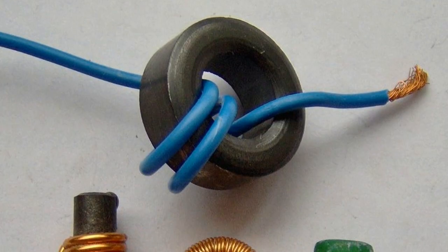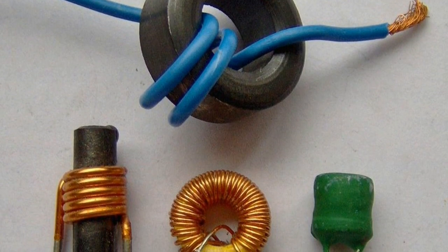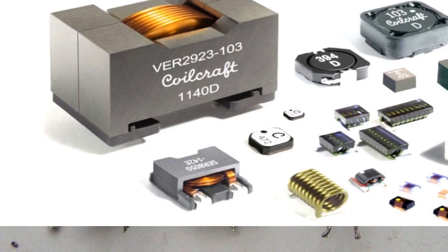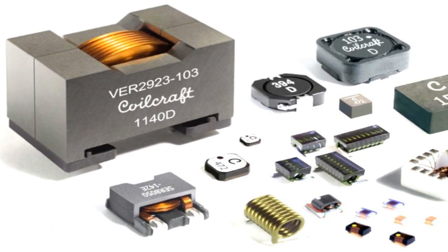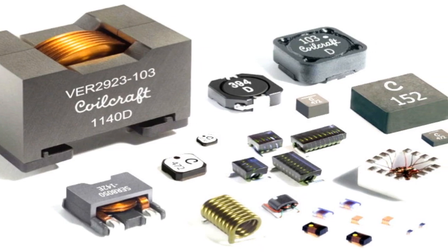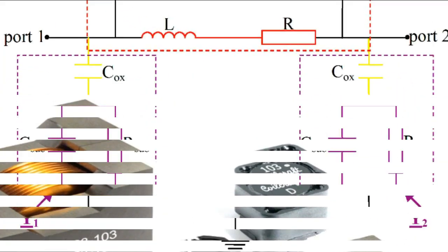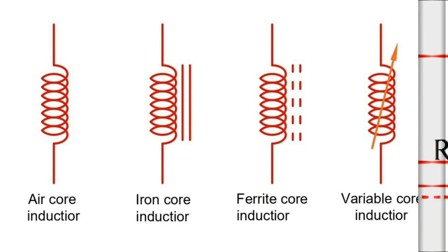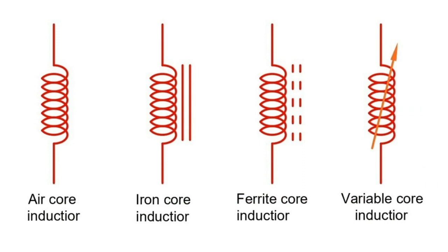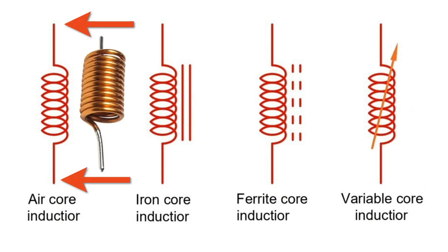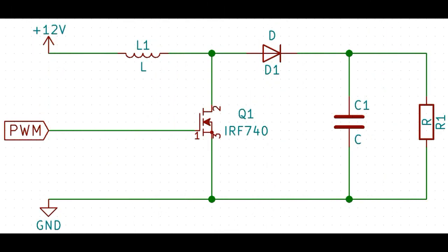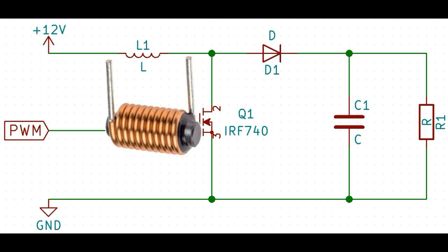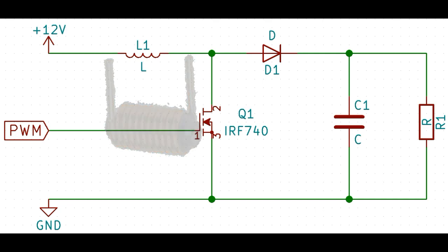Inductors are formed with wire tightly wrapped around a solid central core, which can be either a straight cylindrical rod or a continuous loop or ring to concentrate their magnetic flux. In circuit diagrams, an inductor is represented by a coil or loops. It typically looks like a series of several closely spaced loops or a coil of wire, often with two terminals. The ends of the symbol normally indicate the terminals where an inductor can be connected to a circuit.